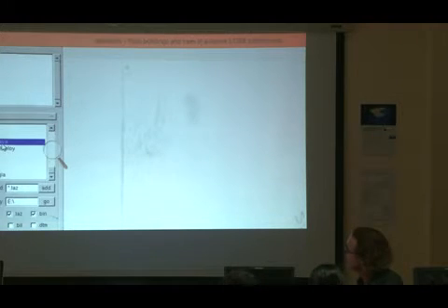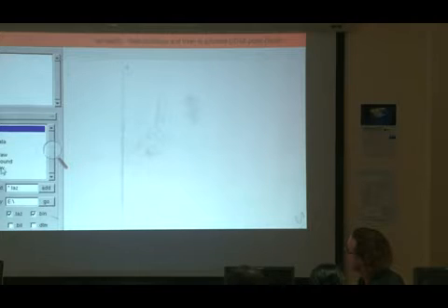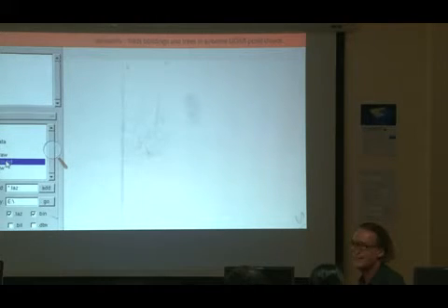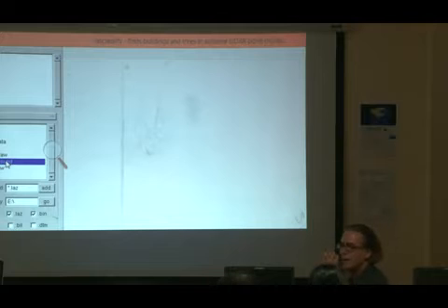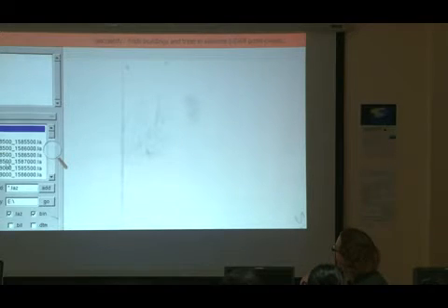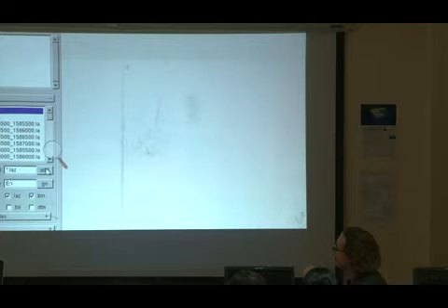I just load the data now from Ayutthaya. I load the ground classified data. And it's important that we click that one button which was called compute height, because that is expected from lasclassify. If you read the README file, it says so very clear that the height needs to be stored in the user data field, which is exactly what compute height was doing.